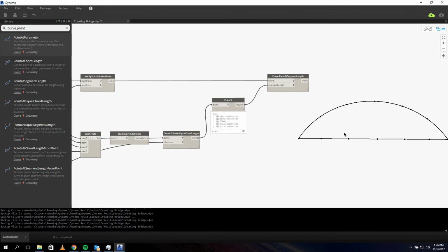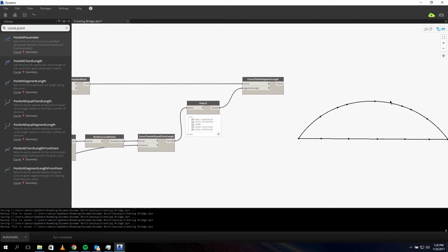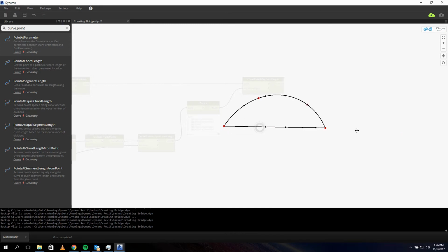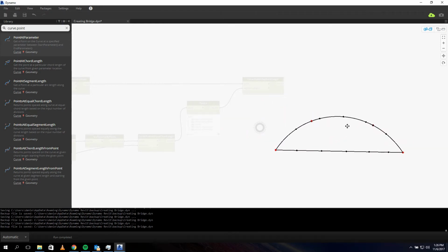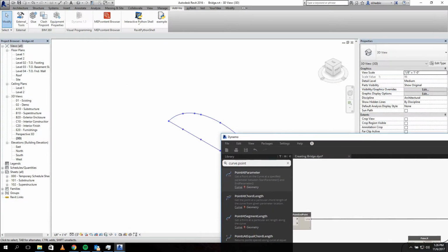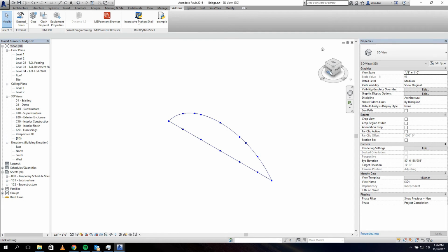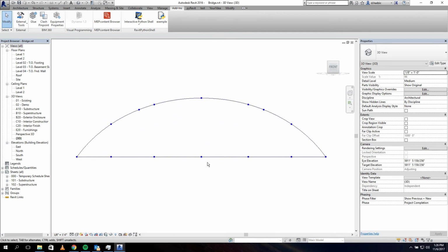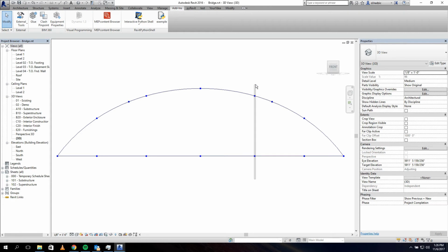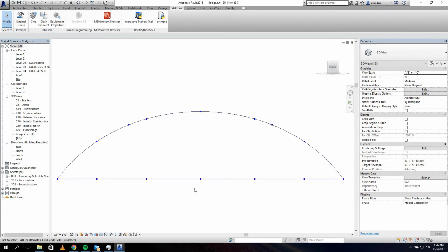And if you go back to Revit, because you cannot see it really well on this picture, because I can rotate my bridge, so I don't know if it's straight above our top point. So let's go to Revit, where we can see it. Go to Revit and we say front view. You can see that it's exactly on top of each other. This one as well. And that's what we need. That's what we want, because we don't want to have weird angles on our supporters.